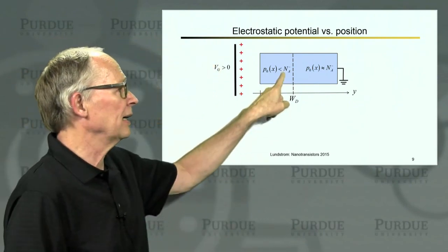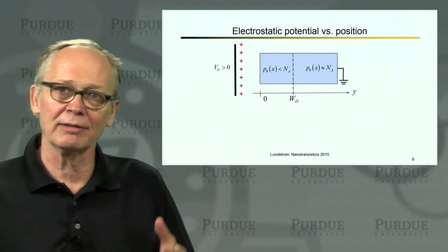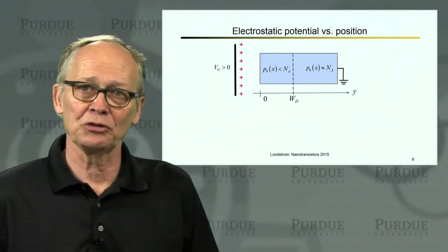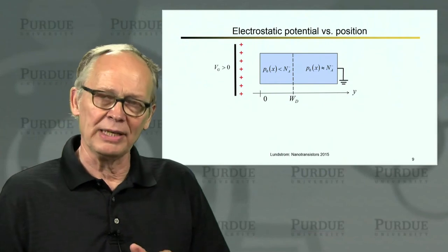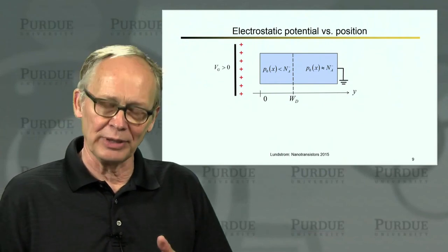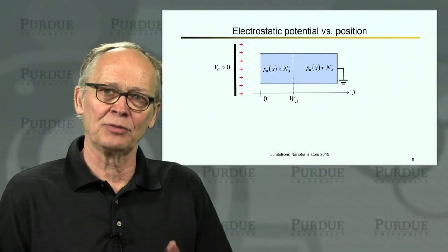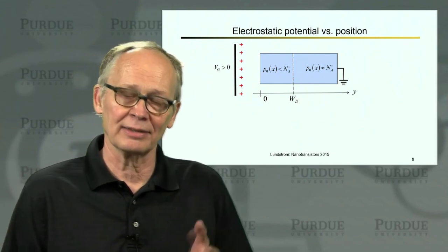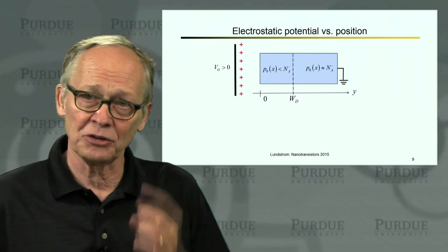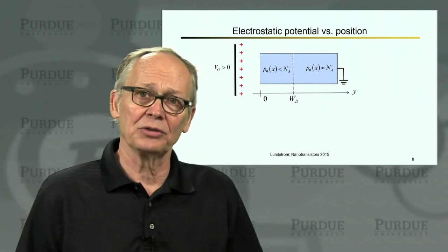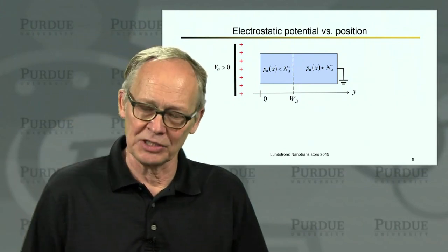But what's left behind are the p-type dopants that were there and gave us the mobile holes to begin with. Each one of those p-type dopants from column 3, which had 3 valence electrons, acquired an additional 4th electron when it doped the semiconductor and created a hole in the valence band. So each one of those acceptor atoms is negatively charged.